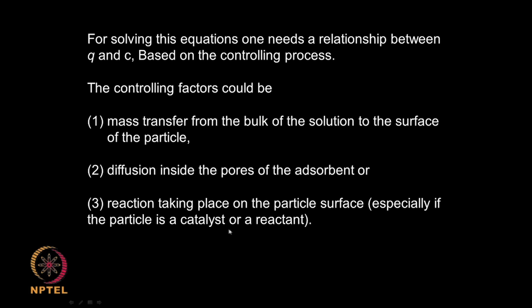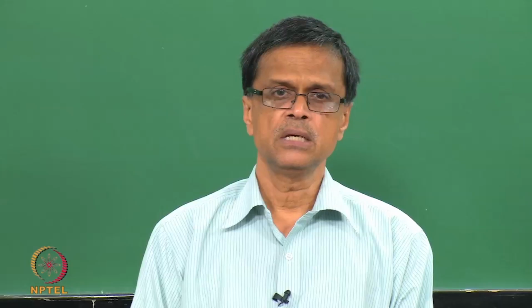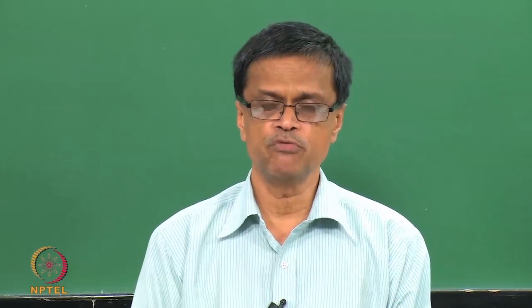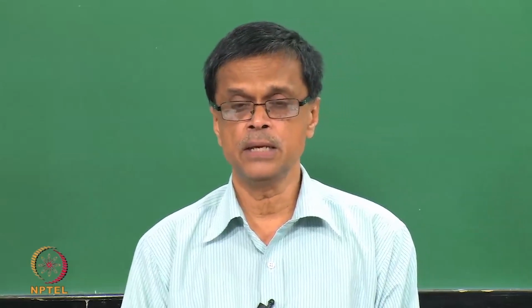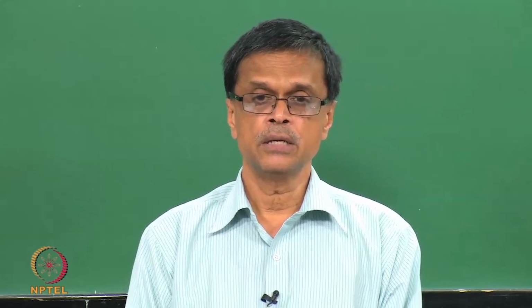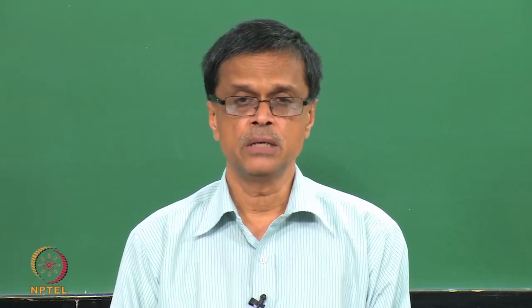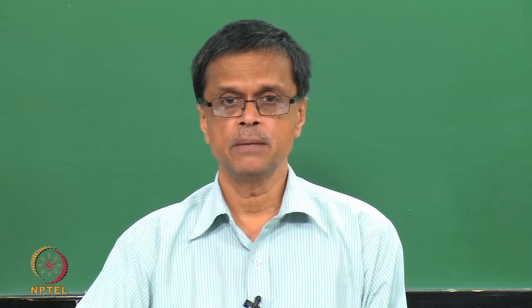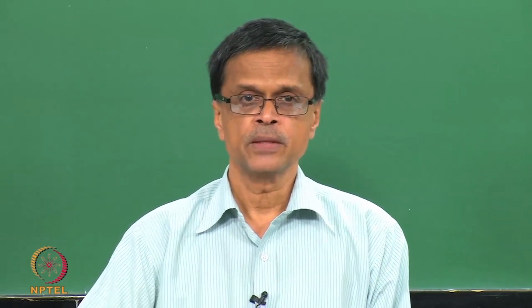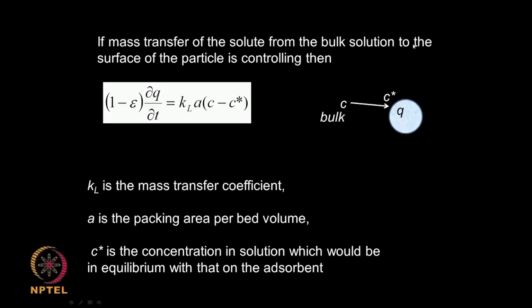Then if there is a reaction, then of course you will also have a reaction, but in chromatography we are not talking about reaction. So, we can completely ignore this. So, two things can happen. One is the mass transfer of the solute from the bulk solution to the surface of the particle, and then diffusion inside the pores, that is called the pore diffusion, especially for example in gel permeation chromatography where the solutes diffuse inside the pores, this term may become important also.